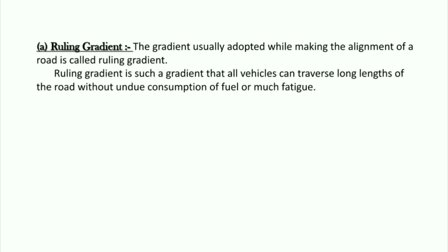So first, ruling gradient. The gradient usually adopted while making the alignment of a road is known as ruling gradient. Ruling gradient is such a gradient that all vehicles can traverse long lengths of road without undue consumption of fuel or much fatigue.